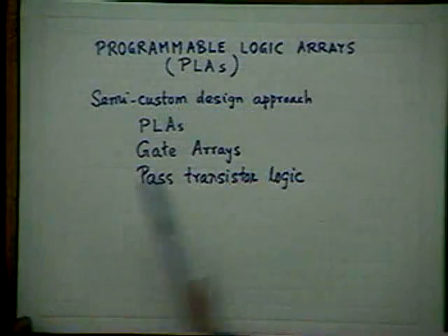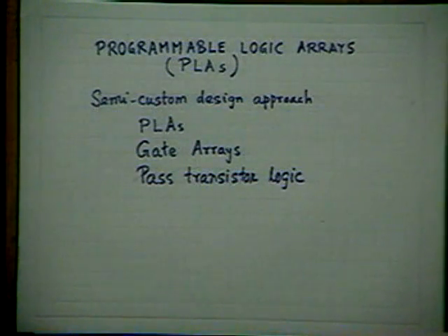But in pass transistor logic, I think you have already remembered that there is a problem. When so many pass transistors are connected in series, there is a degradation of voltage from one transistor to the next, and it suffers from the noise margin problem. So that's one typical problem of pass transistor logic if you want to realize a very large circuit.